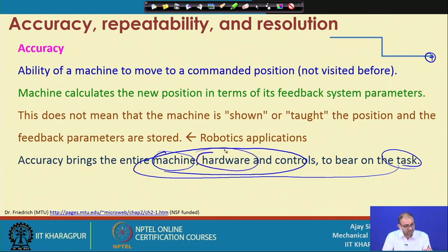Hardware is important because it relates to all the x and y direction movement, that means the servo motor and stepper motor you are using. Those things are hardware. Controller means what is rotating or moving these motors, such as variable frequency drives. If all these things are working at 100% of their capacity, there is a high chance that you will reach the target point. If even one of these is not working at 100% capacity, high chances are that you will end up with the wrong location, maybe here, here, here or here, in any direction. So, that is the problem.